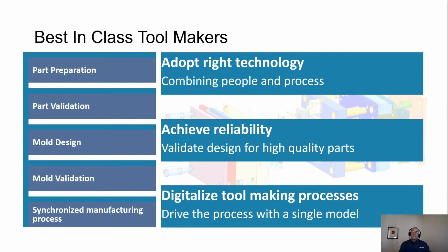So they're going to take out some of that mundane manual labor of taking the file, designing it in CAD, taking it out of CAD, STEPping it maybe, or some sort of file that you can send over to the CAM guys. Those CAM guys are going to try to use that file, but if they don't have all that technology that's been built into it, they may end up rebuilding it. So if you're staying with CAD, you're going to take it over into NX CAM. You could also take it into NX Mold Wizard. So it's all staying together within that same environment.